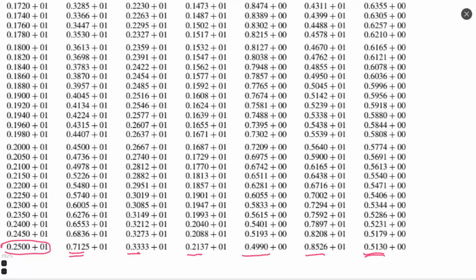We remember that the Mach number after the shock wave is inversely proportional to the Mach number before the shock wave for the characteristic case, right? Just to remind you one more time, M2 characteristic is 1 divided by M1 characteristic. So the bigger the Mach number before the shock wave, the smaller the Mach number after the shock wave.